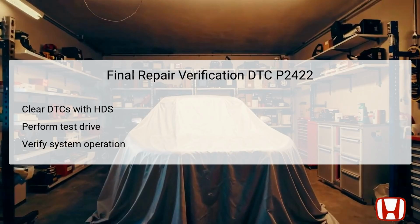Once all necessary repairs and inspections have been completed, it's vital to perform a final repair verification. Start by using the Honda Diagnostics system to clear any DTCs that have been stored due to previous issues. After clearing the codes, conduct a test drive under various driving conditions to ensure that the vehicle operates properly and that no new codes appear.